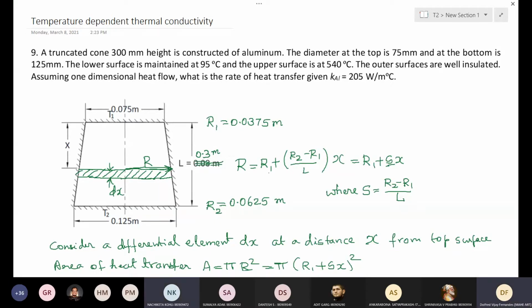So it's 3.5 minus 2.5? No, that is the critical thickness. But if you want the thickness which allows the same heat transfer as the bare wire, then it is 5.136 minus 2.5. Yes, and for the maximum heat transfer, it is RC minus the radius. Yes, exactly. Okay.